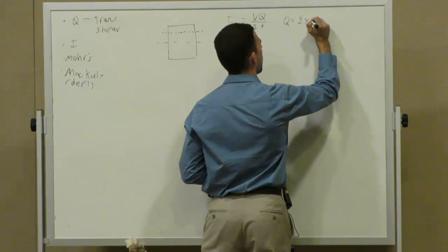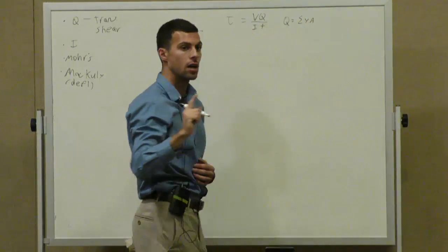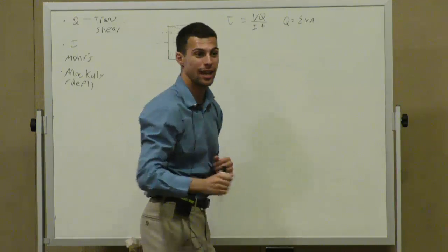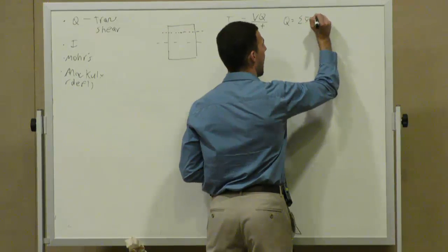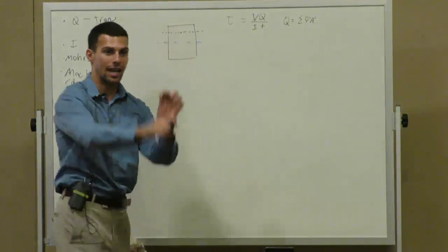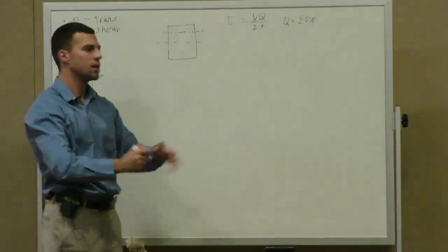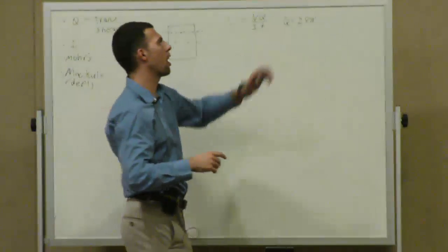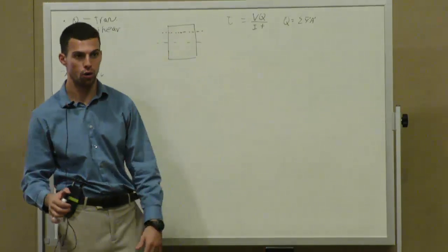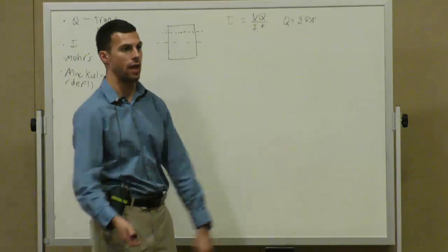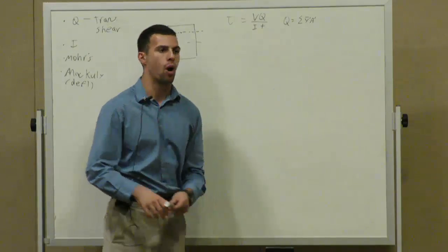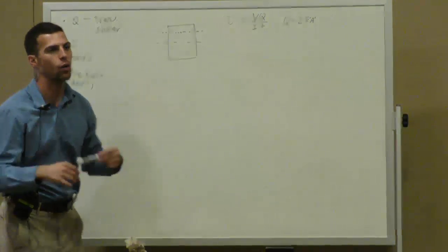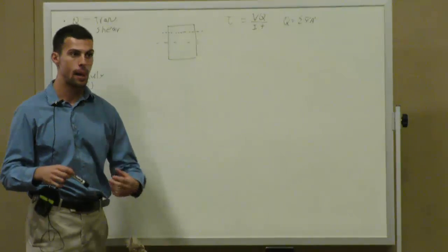Summation of YA. It's both. It is actually Y bar prime A prime. So yes, we're looking at the correct values, just with some different fancy things to establish them. The primes mean that they are not for the overall shape; it is for some other thing. So the A prime is what I call the area of interest. So where is the area of interest for our shape?